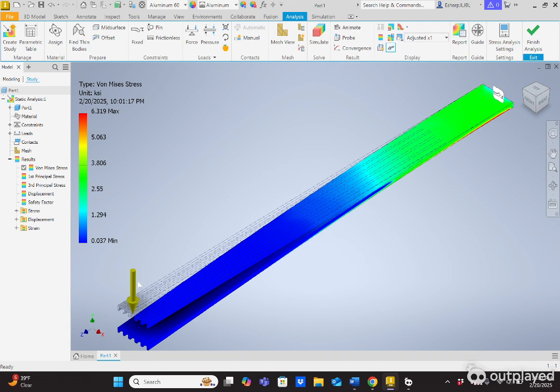And then you can scroll through those, find the flexural rigidity that is most similar to what you need, and slightly tweak the design until you get exactly that E times I value that you want, right? And so I'd recommend doing that for all 10 materials, and then maybe in your paper actually showing the calculations for the 4 that you choose, and especially the best overall.